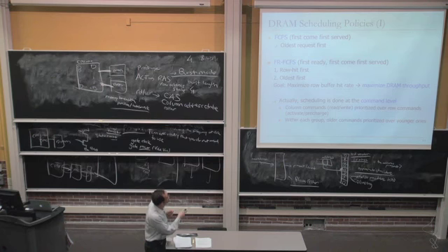Okay? So one way of implementing this FR-FCFS is, if you will, prioritize the requests that are waiting for the column commands. Because obviously, if you're waiting for a column command, you're a row buffer hit. Right? And prioritize them over those that are waiting for the row commands. And within each group, older commands are prioritized over younger ones.